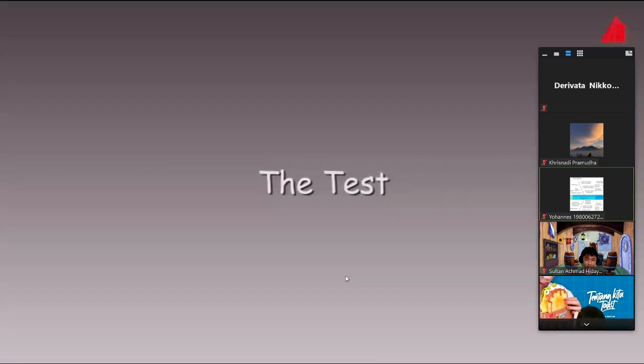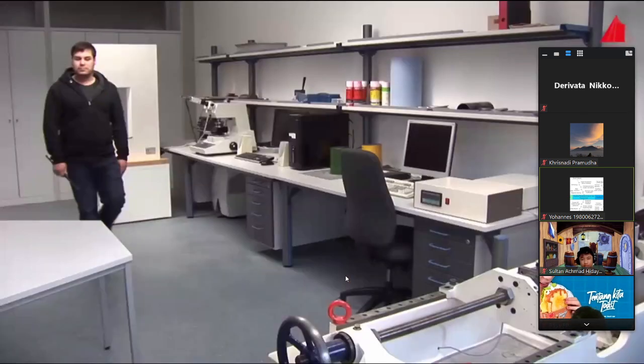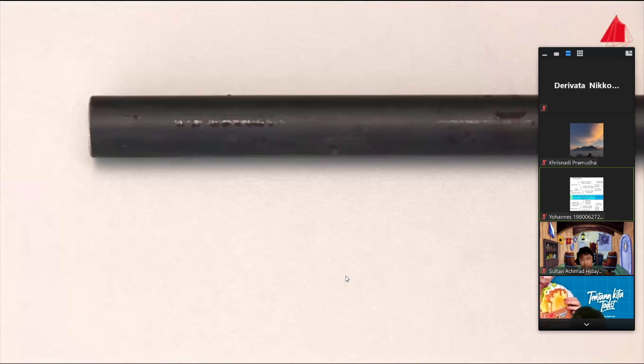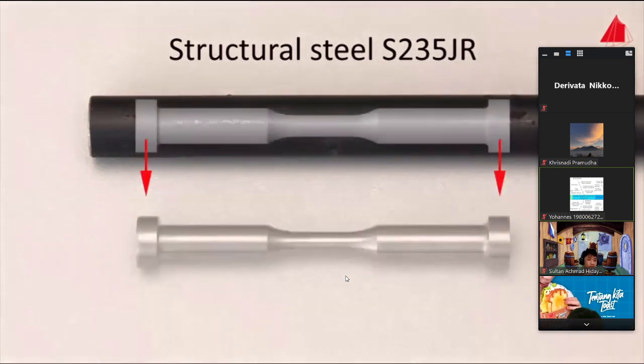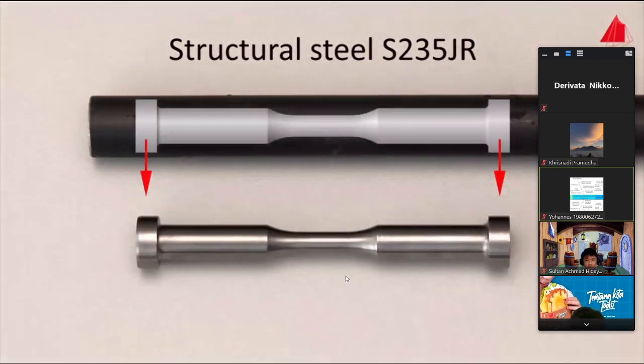How can we make sure that frequently used steel in our laboratory? Hot-rolled steel rods made from the structural steel S235JR are used as base material. In order to eliminate the influence of the surface and to stress the material in a well-defined manner, suitable specimens have to be machined from the rods. This specimen type would be ideal.